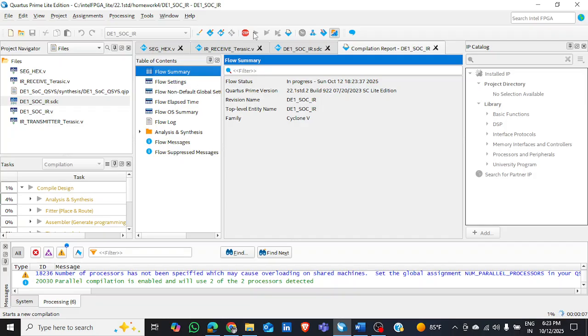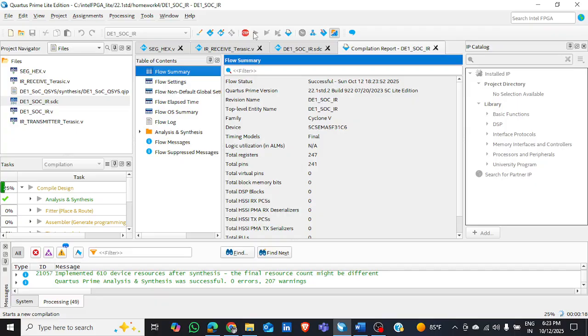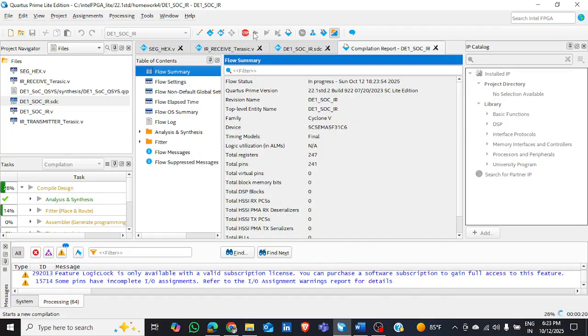Basically part 2 is an experiment to prove that distance equals time on a chip. You use the chip planner to intentionally override the tool's optimal placement by moving connected logic elements to opposite corners on the FPGA. So you create very long wires because you're placing one on the bottom left and then one on the top.